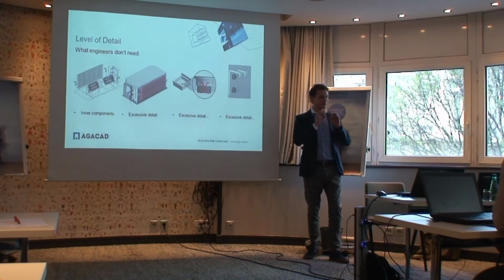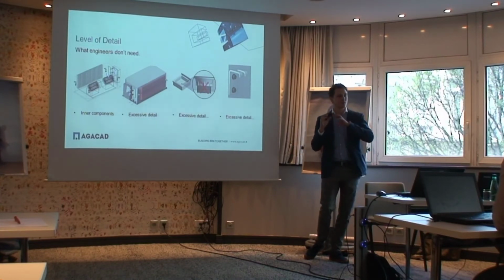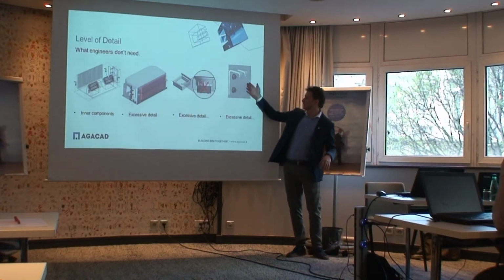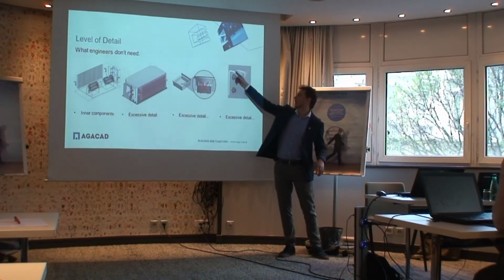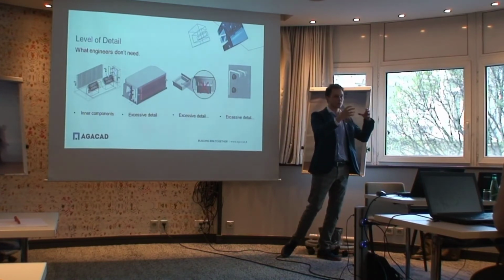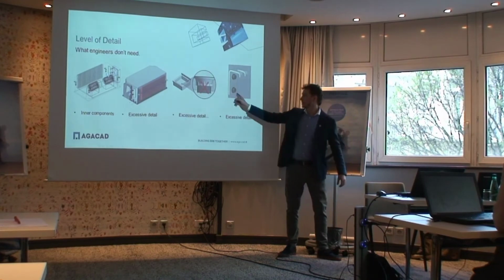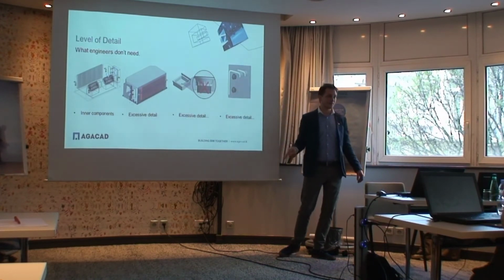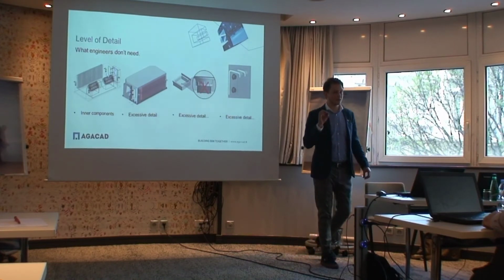So you have to think about the level of detail that your customer will need for each of the elements. At this position, I think I need the connection to the wall, to some structures, but I don't think I need the bolts. And modeling each of the bolts inside of your element takes time.